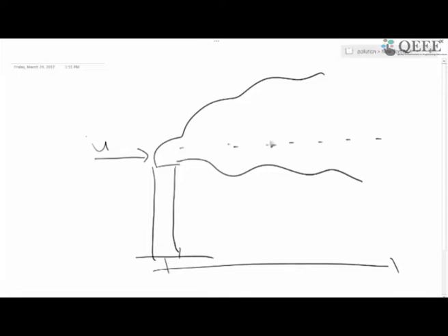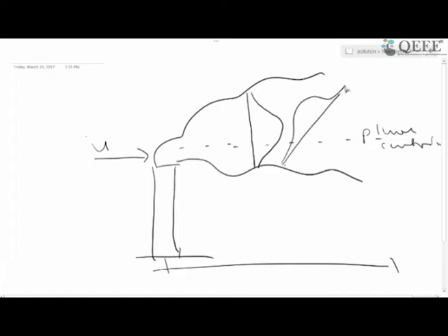This is what we call the plume center line. So the dispersion can take place in those two directions: dispersion can happen here and also in the lateral directions. The spread will be determined with sigma y and sigma z, which will be estimated with this chart.